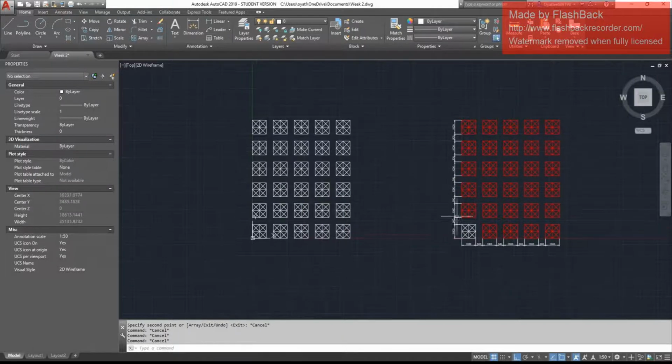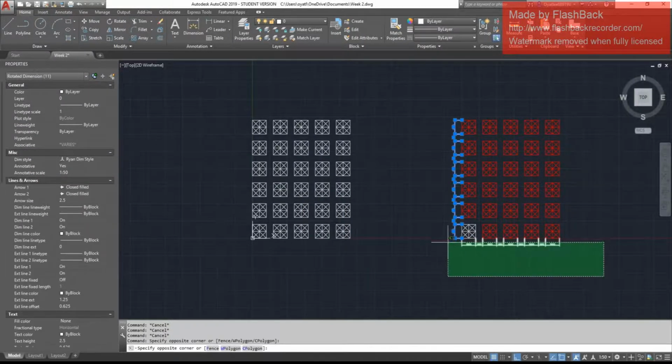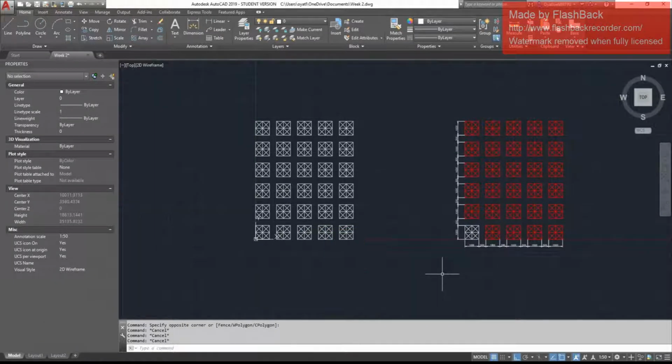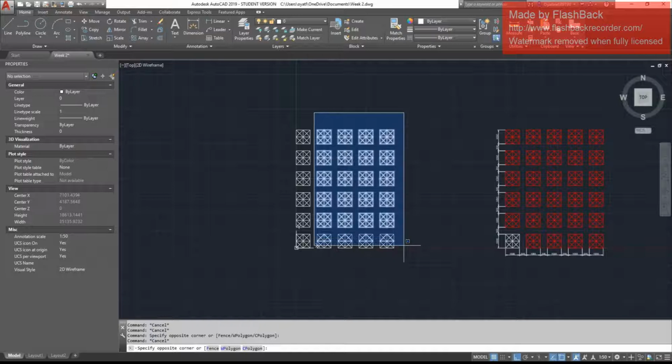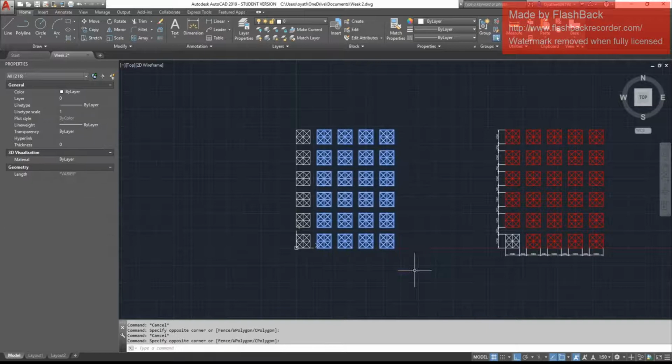And I forgot to explain how to place those dimensions and the move command, because move shouldn't have any of this dimension written on your paper because it's already moved, which means you don't have any original object remaining. The copy is a bit different because now you do have your original object and copied object all remaining on your screen, right? So let's go and change this color here to red. So go and click one point, release your hand from your mouse and drag it down and click the other point, and then the 1, 2, 3, 4, 5 on the top left is still in white color, which is not selected yet, and do another selection.